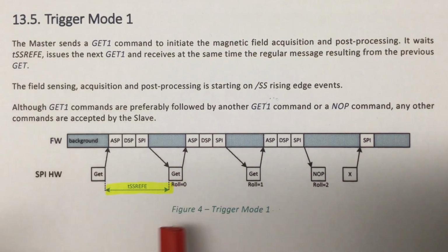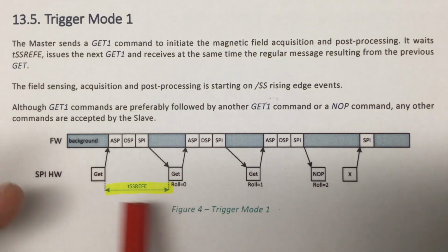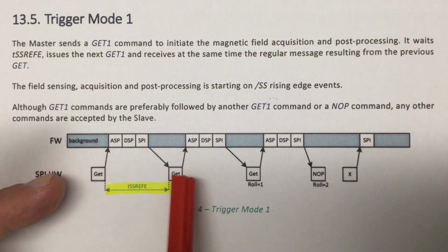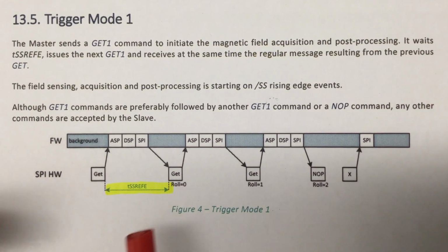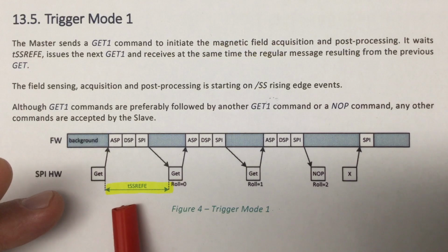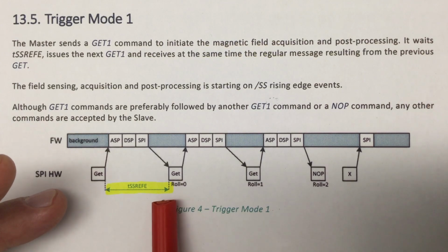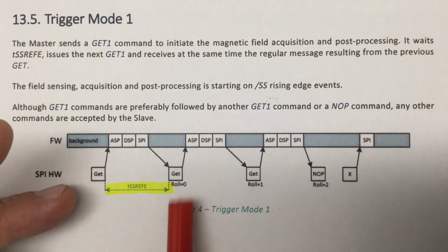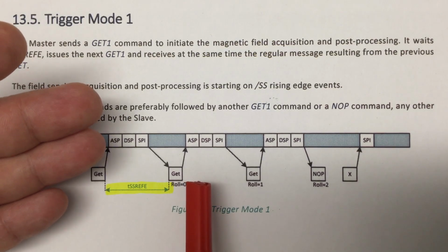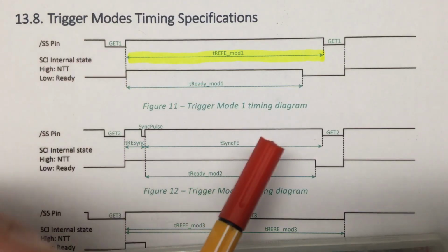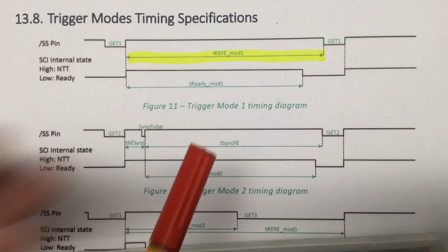And I moaned about that the minimum time between 2 of those SPI transactions is only referred here in the datasheet as T_SSREFE, and that this value is nowhere else mentioned in the datasheet. The reason being, it's probably a typo in the datasheet.